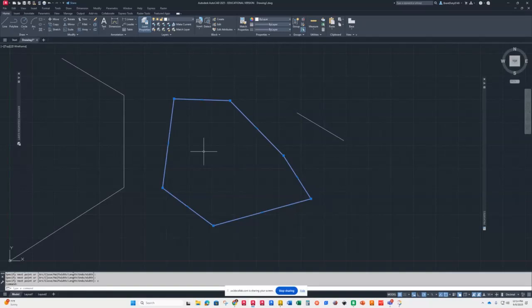And the reason for the last one, normally I don't do that. I don't use the close command. But the thing with a polyline is you have to keep going or it messes up anyway. So the reason that I do the close on this is because if I were to go in and edit this and change the thickness of it, which later on we can with p-edit, then if I don't close it, it has a weird looking corner on it, basically.